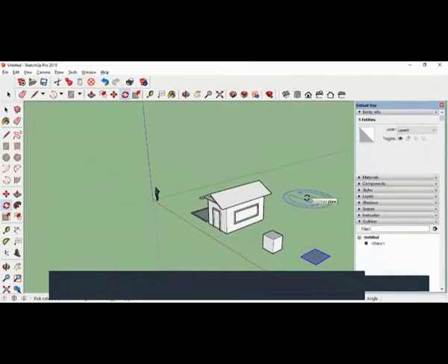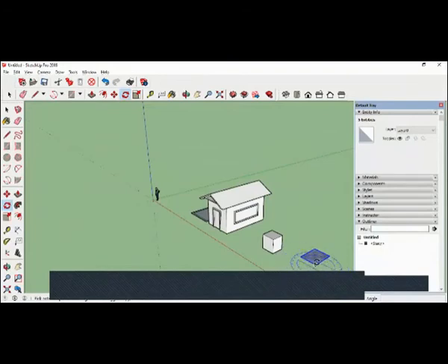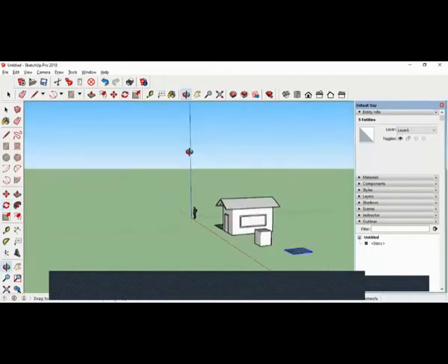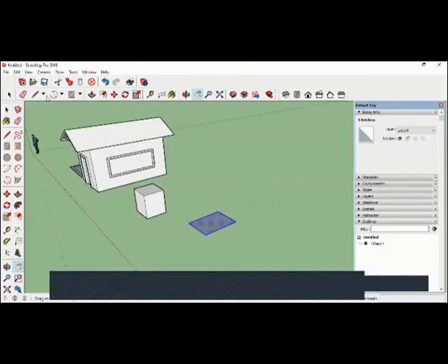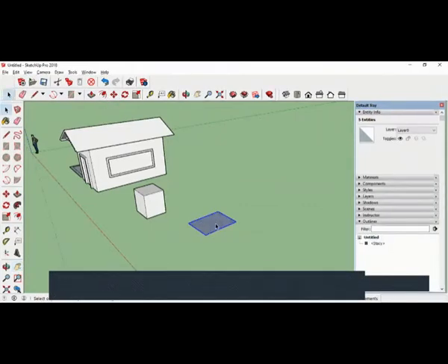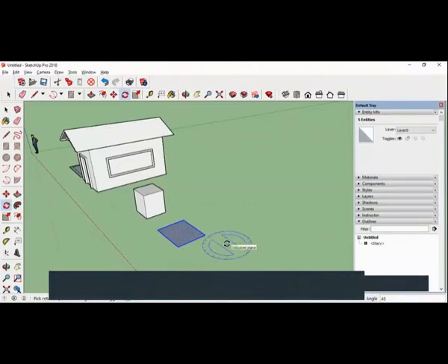So immediately you get a protractor-like object. You click a corner. Now you want to rotate like this. So click here, click. Let me move this a little. So I've selected the object, rotate, click the corner, show a horizontal line like this. Now we are showing a line parallel to red. Click. Now you rotate whatever angle you want, say 45 degrees. If you rotate again 45 degrees, it will become 90 degrees. So you can rotate the object using the rotate command.